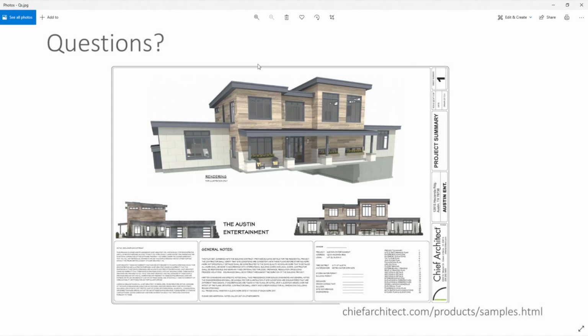Right. Or just use the auto build feature to help the framing side of it, because sometimes the framing gets a little squirrely. Yeah, I think if you figure out how to configure the wall properties, they will generate the model so you don't have to click on any wall and pull it up or pull it down.